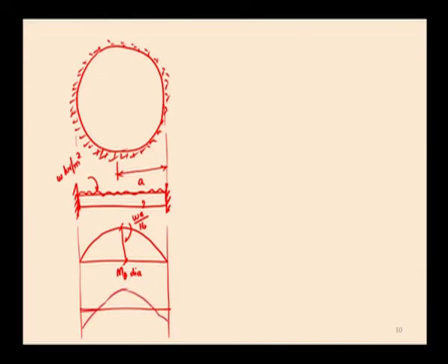This is the deflection nature; normally at the edge, the slab will be deflected at the fixed end. Here it is minus 2 by 16 W a squared, and this one is positive, W a squared by 16. The distance of the point of zero bending moment from the center of the slab is a by root 3.